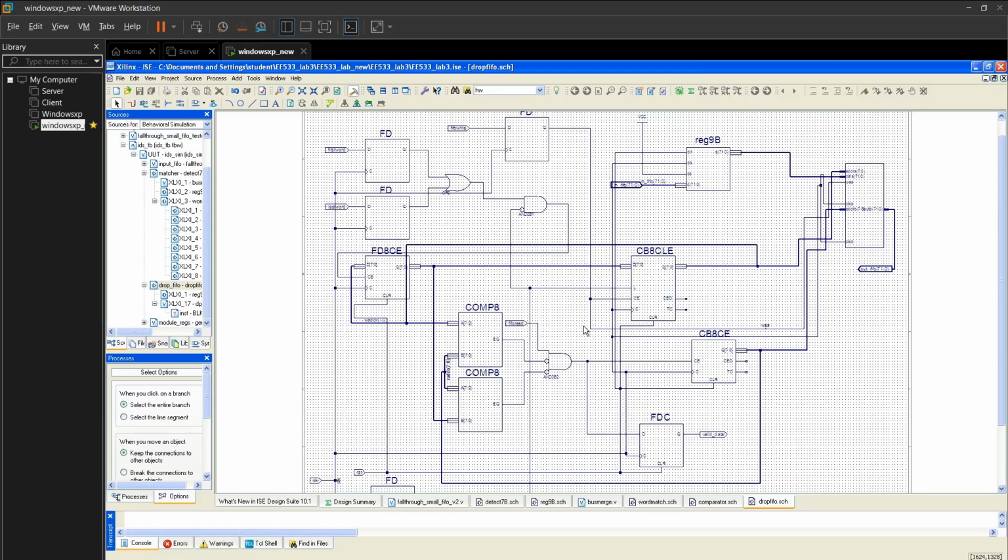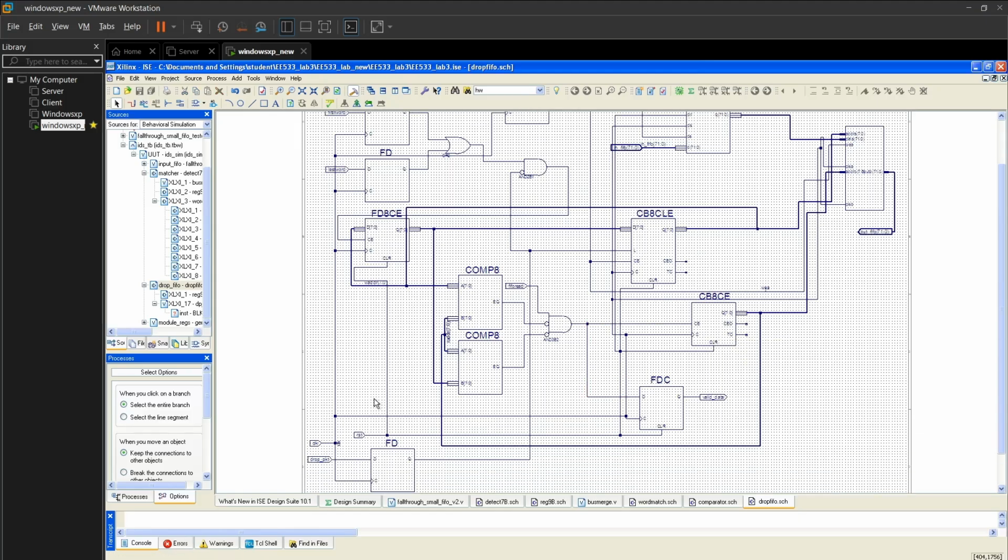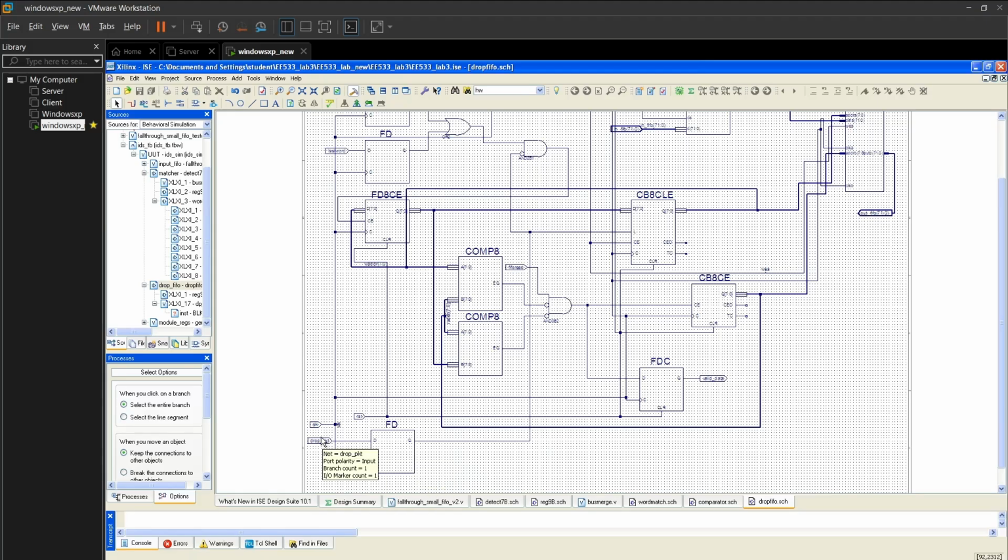So that's the main design over here. As you can see, it's also connected so that you can't have a read address increment if it's the same address, you don't need to increment it. So for that, we're having a signal. Similarly, we also have another D flip flop for drop packet.